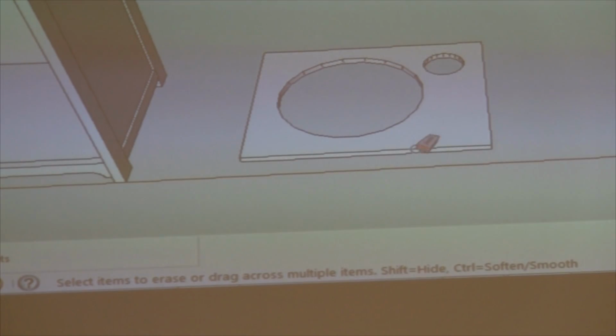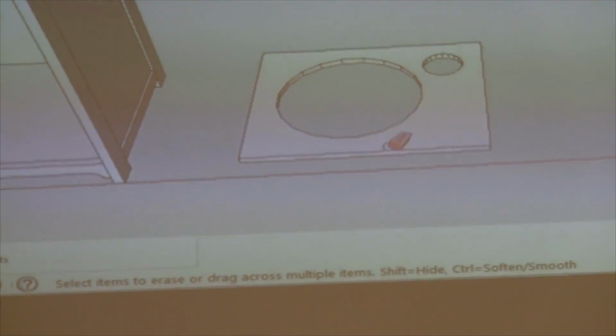It does work. Now, when you did that push pull on that last double set of circles, you just double clicked after you told it to move that small one, and it did the large one automatically? Yeah, there's a shortcut for push pull. After you move any surface down a certain distance using the push pull, it remembers that distance. So whenever you use a push pull the next time and just double click, it moves it that same distance. But you have to be careful because, let me show you over here.